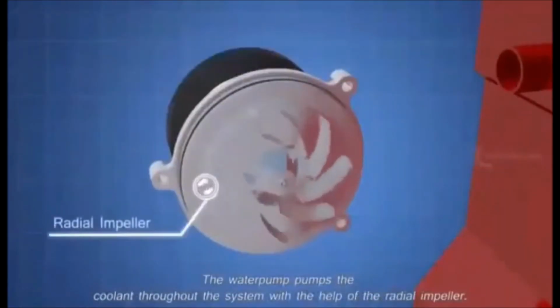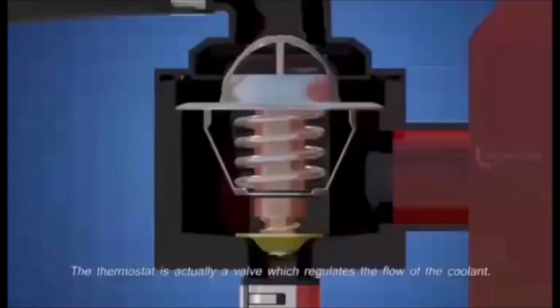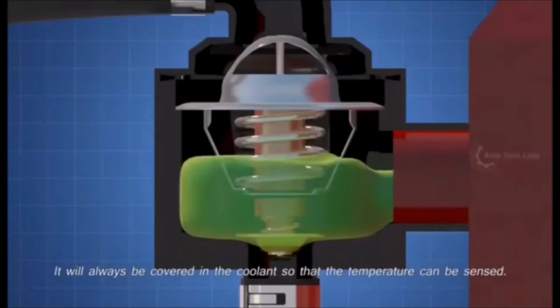The water pump pumps the coolant throughout the system with the help of the radial impeller. The thermostat is actually a valve, which regulates the flow of the coolant. It will always be covered in the coolant, so that the temperature can be sensed.